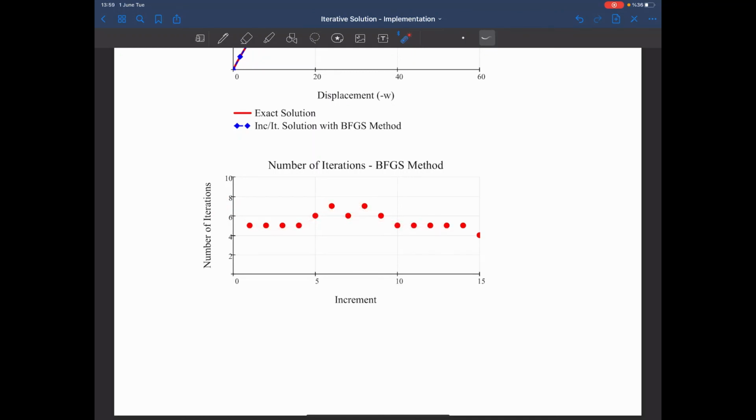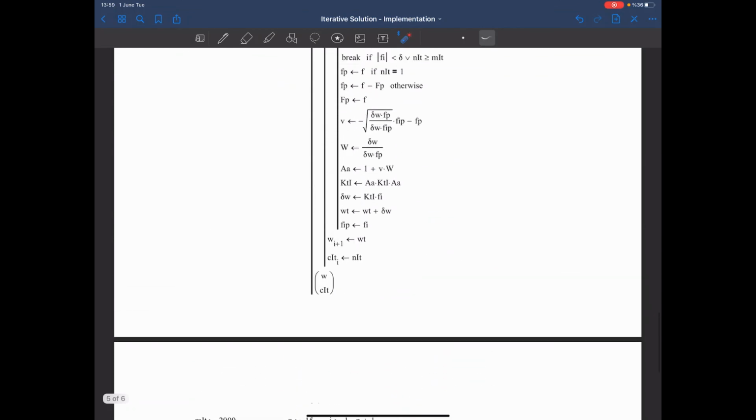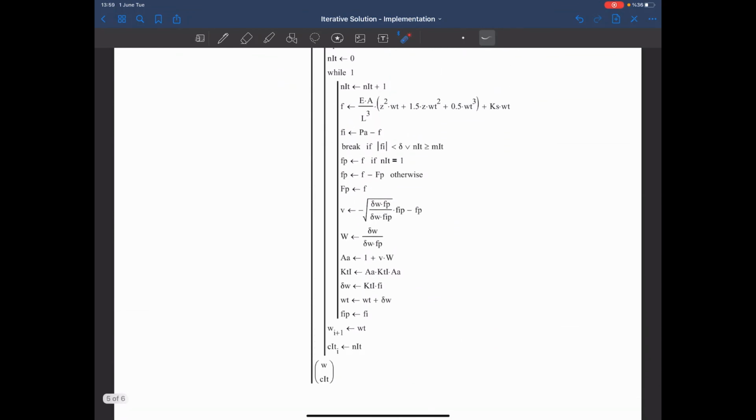than the Newton-Raphson, but computationally it can be argued that it's more effective because instead of doing matrix inversion at every step, you do it once and then you keep transforming it by using the displacement increments that you calculate at every iteration and the residual force.